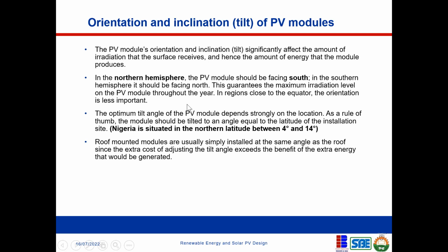Now, when you're facing south, what is the tilt angle? What is the angle of inclination? What is the angle of elevation? Okay, to that south. That's what we're talking about, tilt angle. And this is telling us that your tilt angle should be equal to the latitude of your installation site.